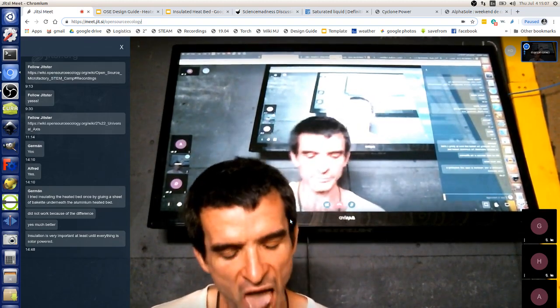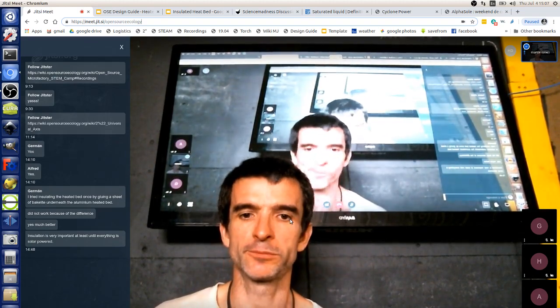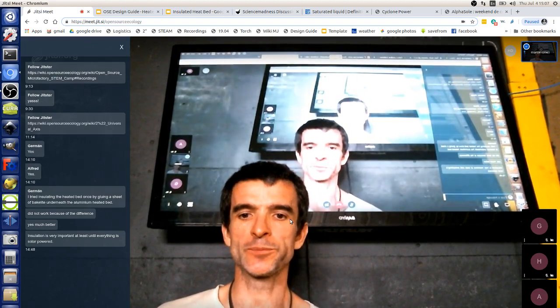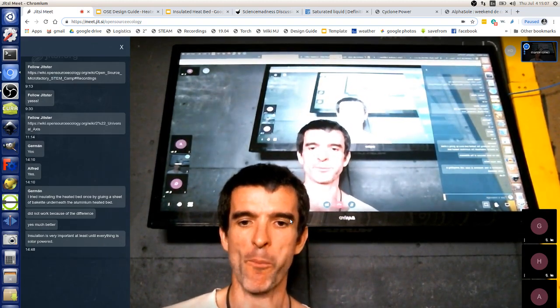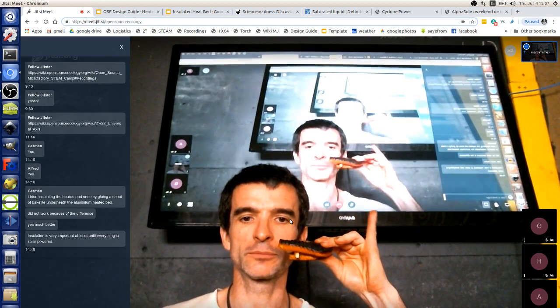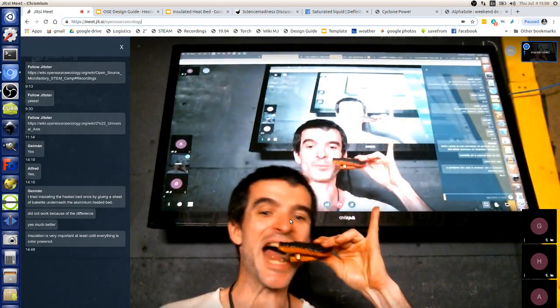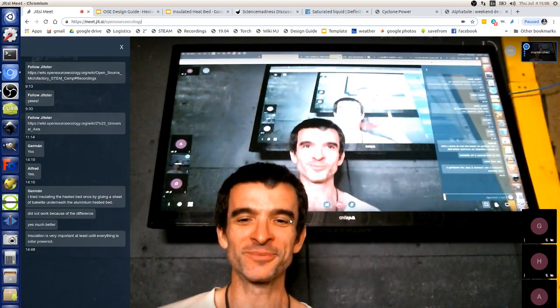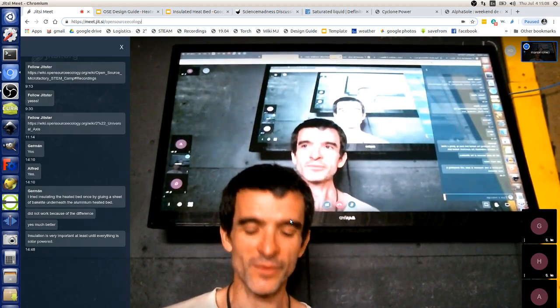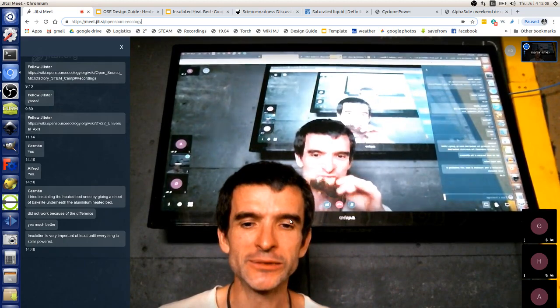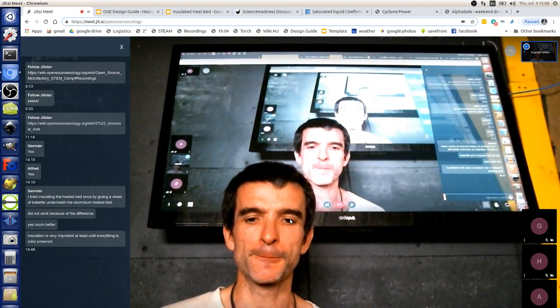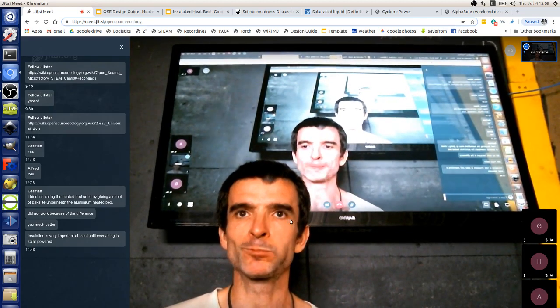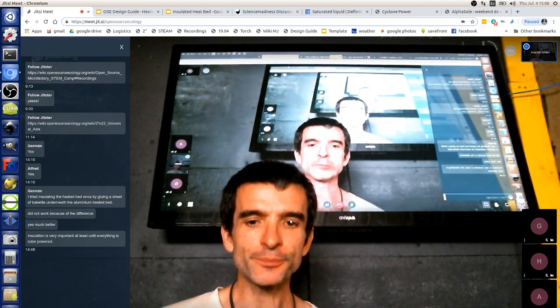Also, like Marcin was saying, you don't have to have perfectly clean water, but the cleaner the water is, the better. In a power plant, I think they use distilled water, as pure as they can get it, because impurities will corrode your pipes and cause additional issues, and will also wear any pump or turbine you're using. You want the smallest number of particles you can get in those kinds of systems for longevity.